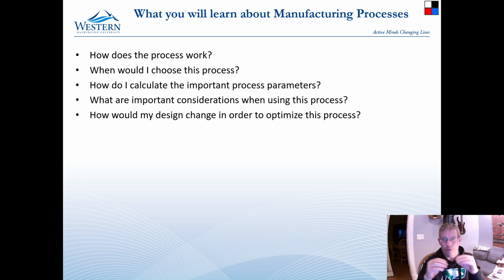You never go from thin to thick because the molecules will expand out and you get very different material properties in that area. So there are just a whole bunch of considerations that you have in that case. Similarly, if you're thinking about designing something for a metal manufacturing process, understanding the process that you're going to use would change the design characteristics of the part. And we'll talk about some of those.